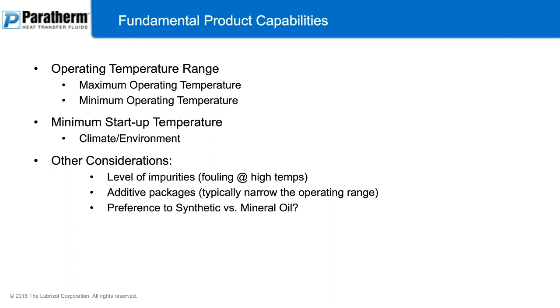So, minimum startup temperature, a key point here. There are times where we get calls and the caller says, I'm operating in a region that features cold weather. Over a long period of time, we have temperatures that get down to negative 30, negative 40 degrees. If the system goes down and we need to perform maintenance, we need to be able to start that fluid back up at that temperature and make it pumpable. The issue is they also need to run the fluid up to 550 degrees Fahrenheit. So your options become extremely limited as to what technology has that wide of a temperature range available to you.